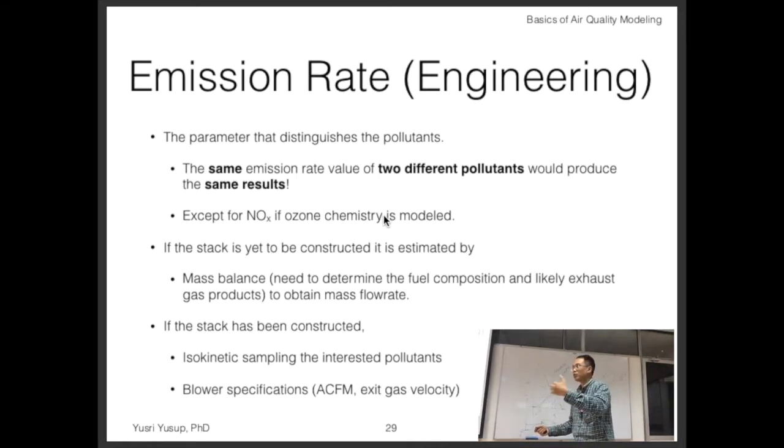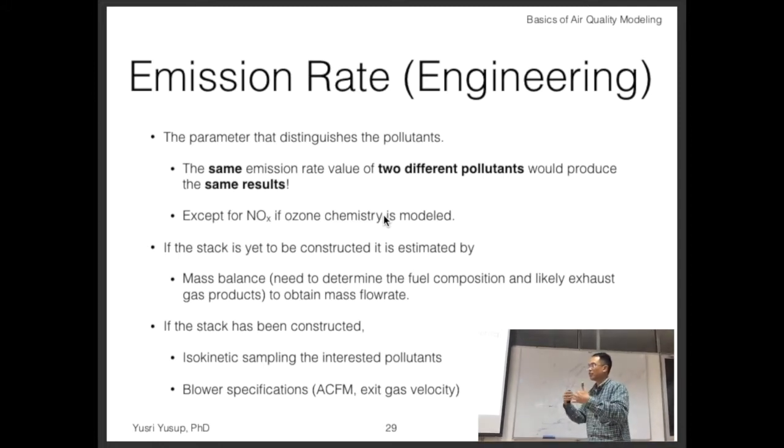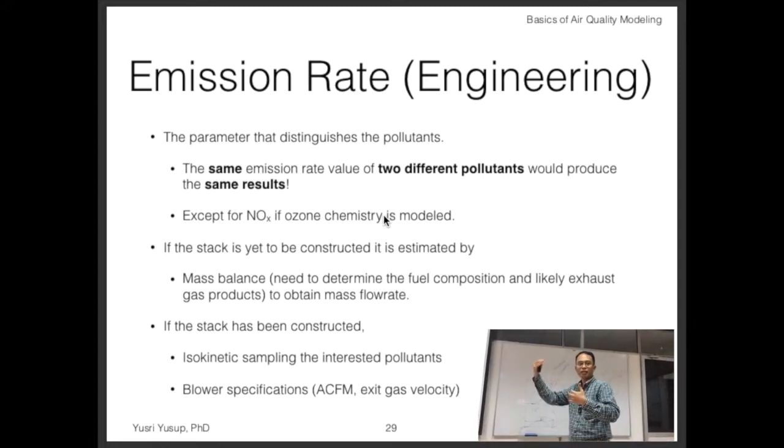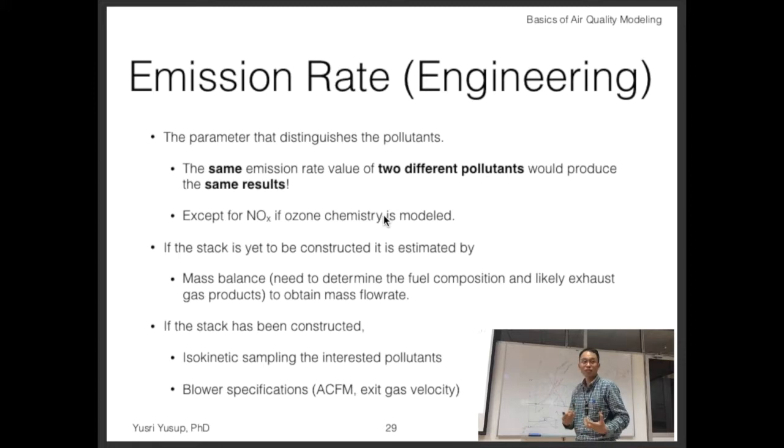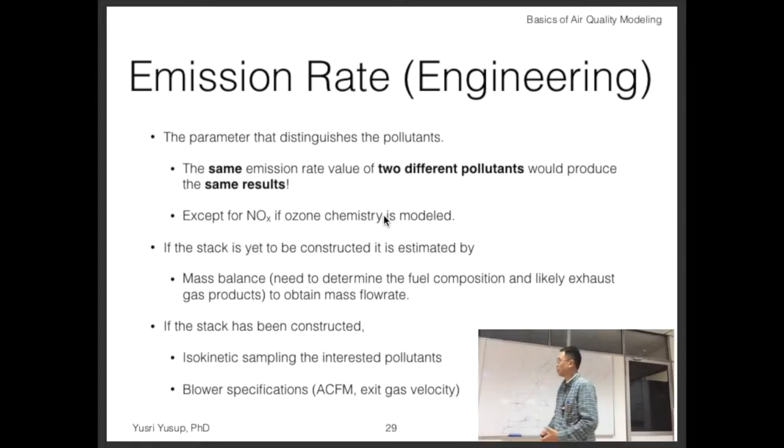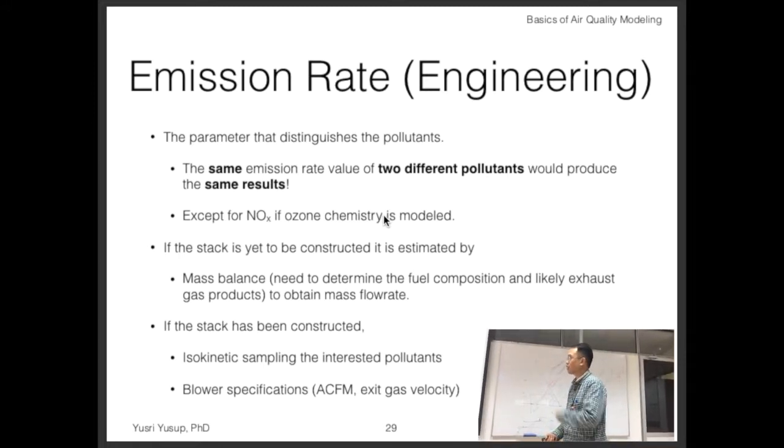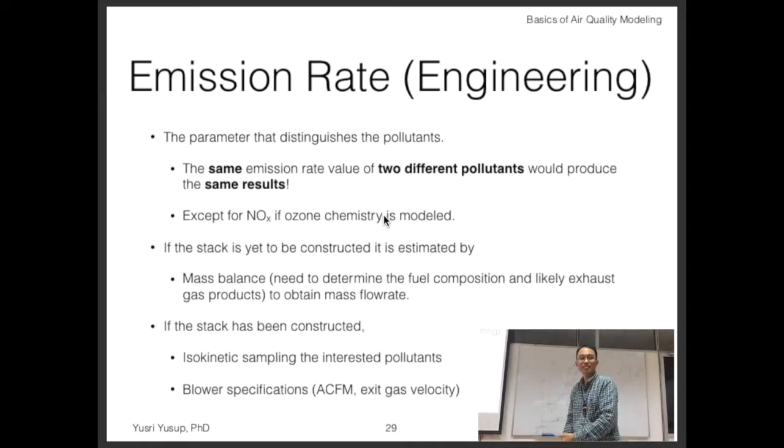Concentration, maybe you want to look at the characteristic so that it's not above a threshold set by the limit set by DOE, Department of Environment. But if you want to put it in the model, it has to be in the form of mass rate. Again, I stress that enough. You cannot just measure concentration. Most of the time when they do tests, they always measure concentration only. But it's not really useful. You need to get the velocity too.